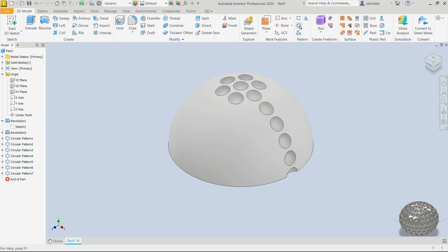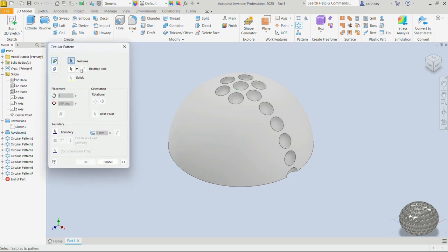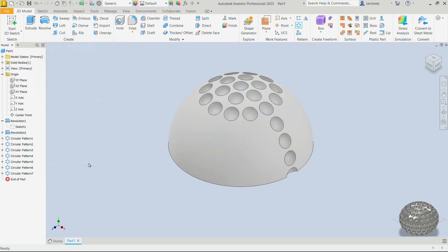We'll do the second one and two circular pattern. First of all, let's pick the feature we want to circular pattern. It's going to be this third dimple we pattern this way. The rotational axis is going to be the y-axis. The occurrences, let me do 12 and see. We would be freestyling at this point. What I mean by that is for the occurrences, we'll just do what works for our golf ball. 12 I think is fine, so we will hit OK.